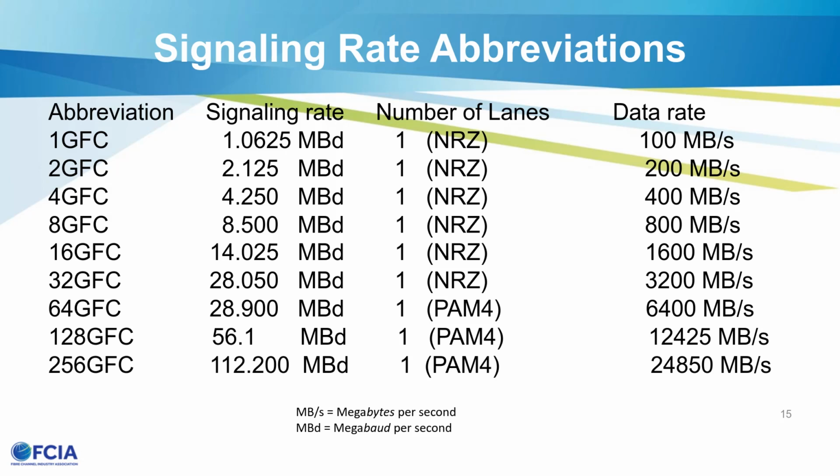One of the other things, it didn't come about accidentally either. It was picked so that, as you look at backward compatibility, which is really important to Fibre Channel, you could easily go backward compatible with PLL dividers to the backward rates. And our goal moving forward for 256 GFC, which is the one we've just started on, right now we're saying, look, our plan, based on the requirements we get, is to try to do 112.2. And we'll see as time goes on and we get more input whether there are any issues with that or not.